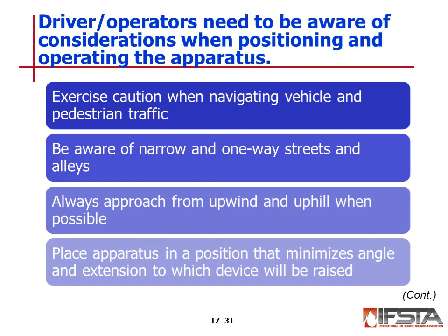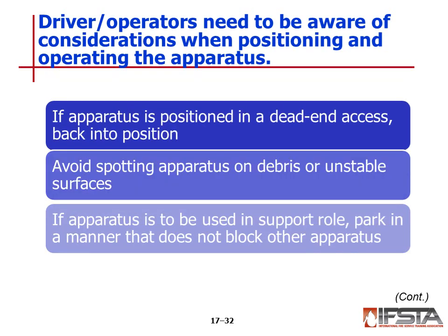All driver operators should consider the following. Exercise caution when navigating through vehicle and pedestrian traffic. Be aware of narrow and one-way streets and alleys. Always approach incidents from upwind and uphill when possible. Place the apparatus in a position that minimizes the angle and extension to which the aerial device will be raised. Driver operators should also consider if their apparatus is to be positioned in a dead-end access. Backing the apparatus into position, if possible, will make an escape faster if it becomes necessary.